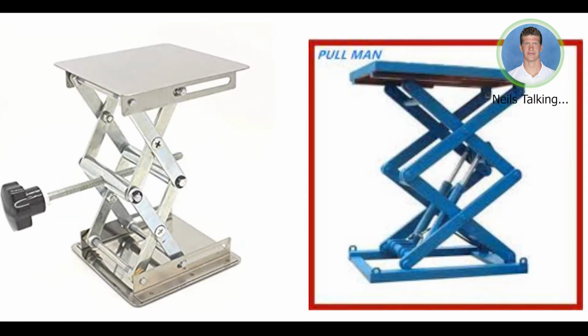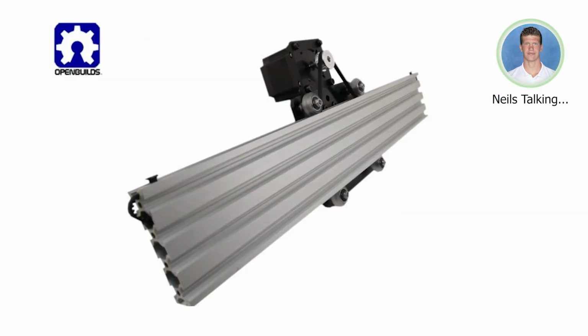The fourth concept is the scissor mechanism. The scissor mechanism can either be driven by pneumatics or by an electric motor. These two power sources would move the linkages in the scissor mechanism closer to each other, resulting in an elevating platform. Similarly, on the way down, the linkages are moved apart from each other. The fifth concept is the belt and pinion drive actuator. In this mechanism, an electric motor rotates a gear that is connected to a static belt. The pinion basically rolls over the belt and can make an up and down motion.